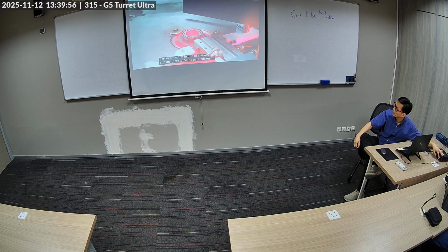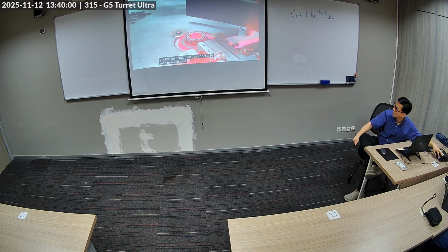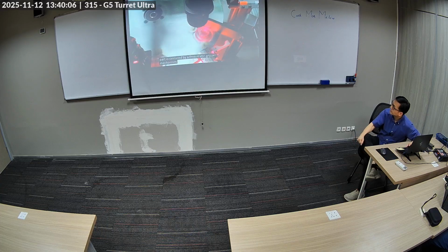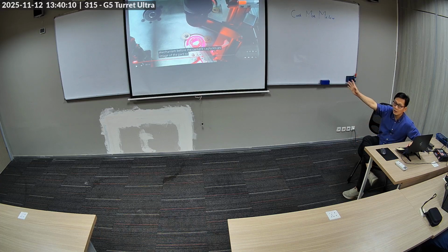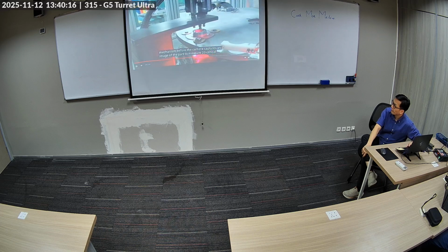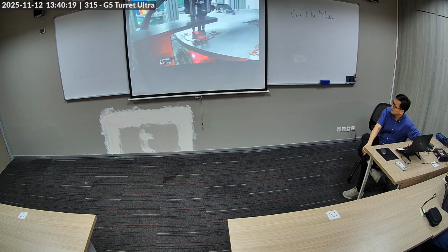The part indexes to the first inspection station under a 16-megapixel camera and custom lighting. The part is centered by a pneumatic gripper mechanism before the camera captures an image of the part. So that pneumatic grip is only to center it, that's it. And then the camera takes the picture to measure 20 critical geometric features.